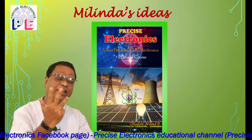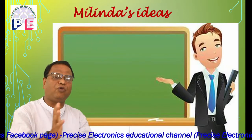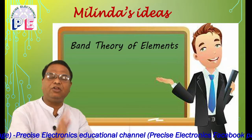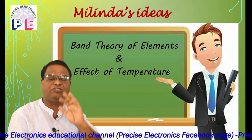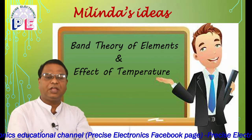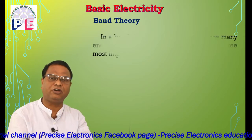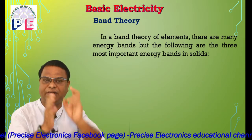Friends, this is our third lecture of Basic Electricity of FYJC Electronics, and in this video lecture we are going to study band theory of elements and the effect of temperature on resistance of element. First of all, band theory. In band theory of elements, there are many energy bands, but friends, the three bands are very important, and those bands are valence band, conduction band, and forbidden band.